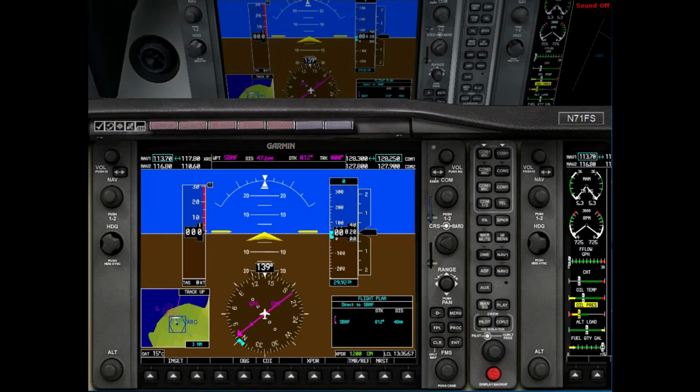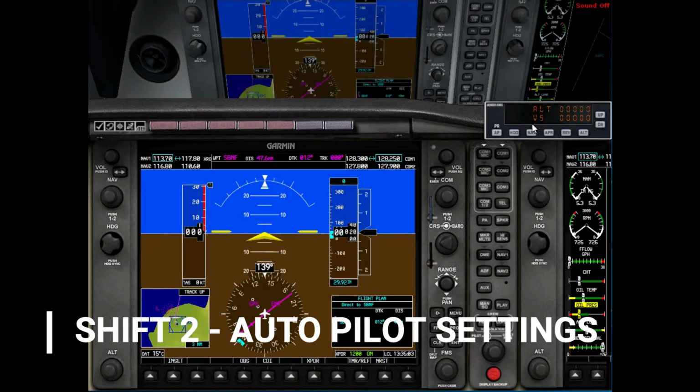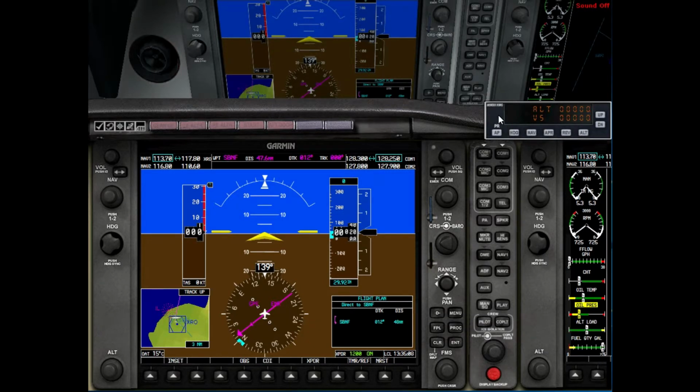Another tool is going to be very useful for us. It's when we press Shift 2 to open our autopilot. We can choose here which altitude we are going to. The rate of climb we can choose. I'm going to take off with 1000 per minute, and I'm going to increase it later. Actually, we're going to 2000, much better. Then we have time to talk.